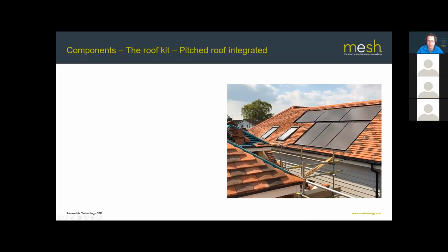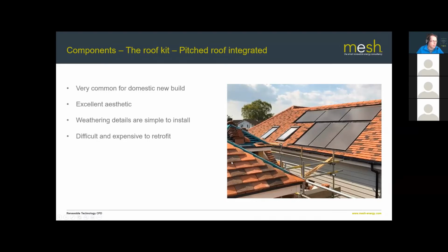This gives a really nice finish, and it's still very common for new build. Good aesthetic, and they're relatively simple to install because you're still putting big panels in, and actually the flashing arrangements are pretty standard, fairly similar to a Velux window, that kind of thing.